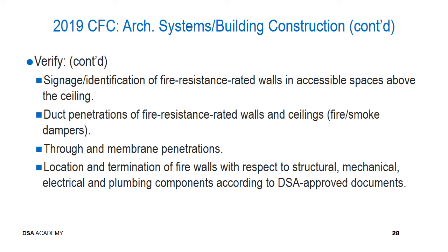Ensure that fire dampers operate correctly and close upon introduction of smoke during testing. Sampling tubes must be verified as being installed in the correct orientation. Ensure dampers are reset after testing. It is not uncommon for fire dampers installed during construction to operate one time and then, around the end of construction, have become askew through other movement of buildings or systems, and they are not now operational. This must be verified.